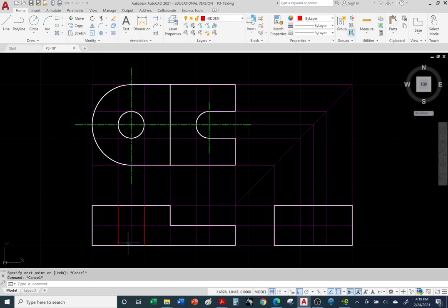All right, so now let's create an axis. So you do need an axis. So from this center, you need to draw a green center line to represent the axis of the hole. Okay, so let's go back to green center layer. Use the line command. Okay, so I know I have to follow the center of the circle above, right? And let's see, click. Okay, good. You don't want to overlap the two views. So I need to make sure there's a space there between the two green center lines. And click and hit escape.